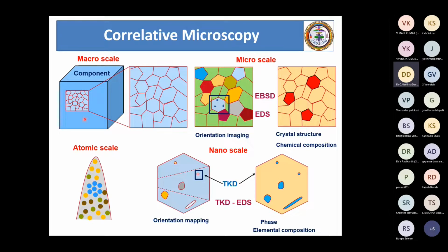That means the bulk sample, same region is being analyzed by all the techniques. From each of these regions that are being analyzed, we are now going higher and higher in magnification by preparing samples from the location identified from the earlier analysis, and then extending till the atomic resolution, all happening on the same sample, same region of analysis, and same volume. Therefore, we can correlate all the information of crystal structure, orientation, chemistry coming from the material at the same time.